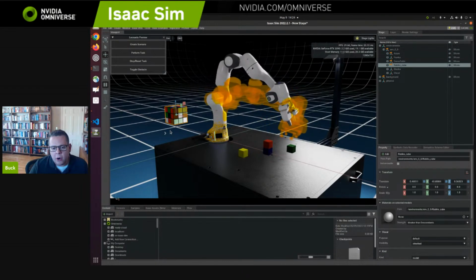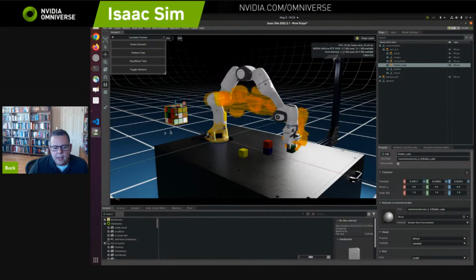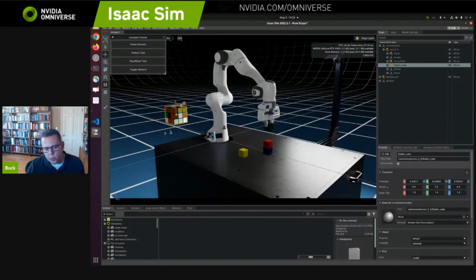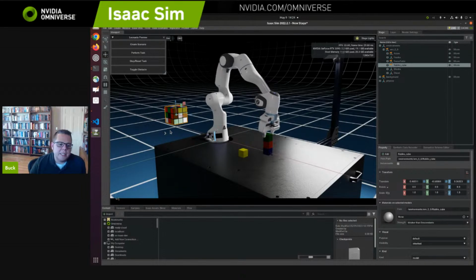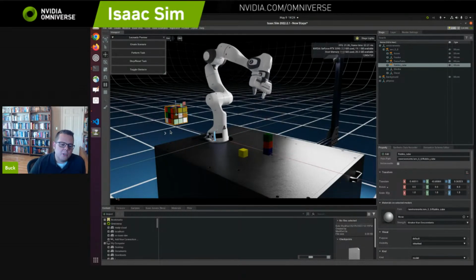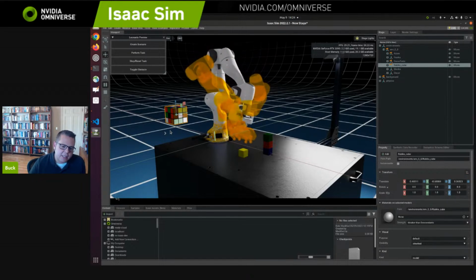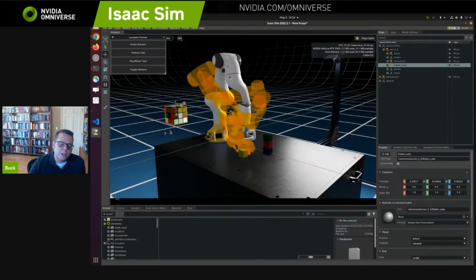So I mentioned that there are all of these different forces acting on the robot at one time. In general, we refer to those different terms as RMPs. So you'll hear me talk about a target RMP that's moving the end effector towards a target, or an obstacle avoidance RMP. So there can be any number of RMPs. You sum up all the contributions. You do some math involving the sum of the metrics, which I mentioned, and that gives you a final desired trajectory for the robot.